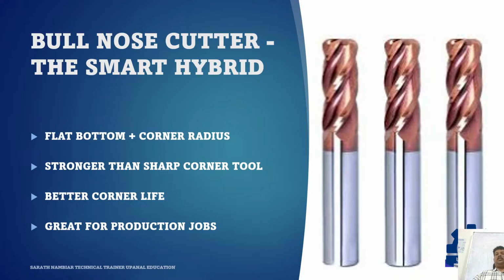The bull nose, also known as the corner radius end mill. This cutter combines two useful ideas. It's mostly flat bottom like a flat end mill, but instead of sharp, fragile corners, it has a small radius at the corners. Why does this radius matter so much?